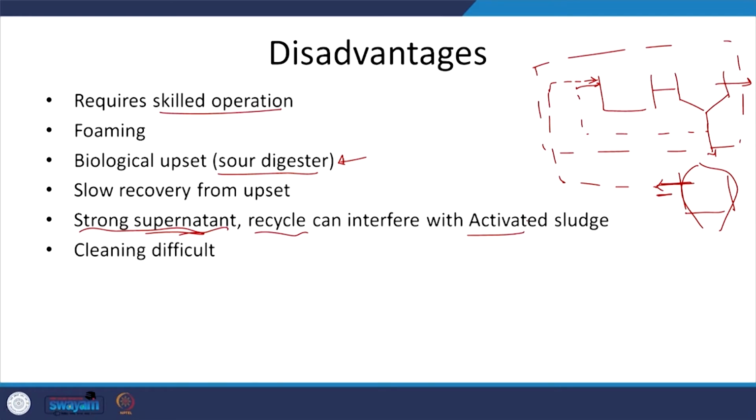So, cleaning is difficult obviously, and the initial cost is high. For example, for kitchen waste, let us say, I am just talking about some rough numbers. For IIT Roorkee, kitchen and relevant organic waste is estimated to be 2.5 tons or 3 tons for the 16,000 population. And for that, if you can get it at a fair price, the anaerobic digester system will be around 60 lakhs or so. So, that is one aspect to keep in mind, right.